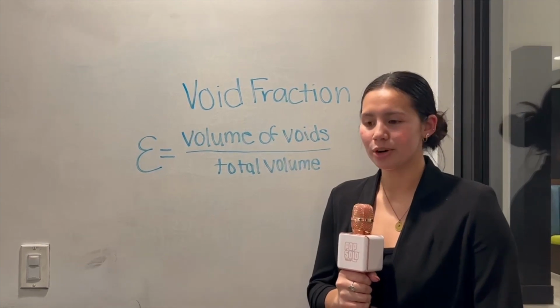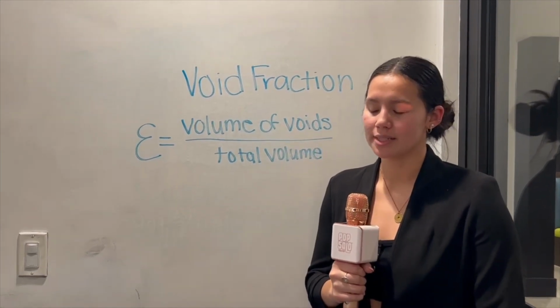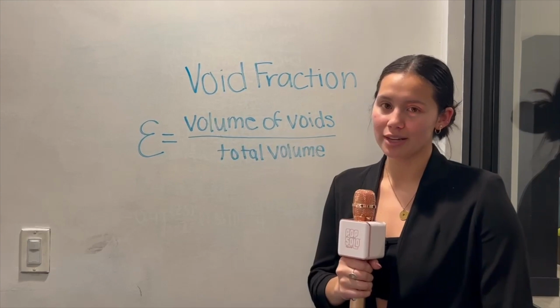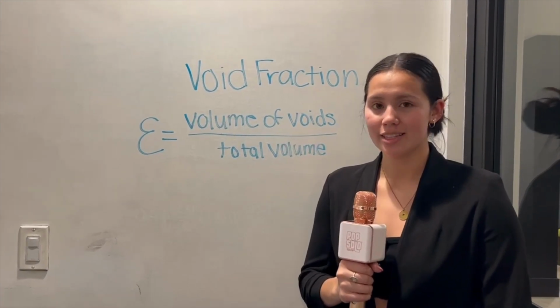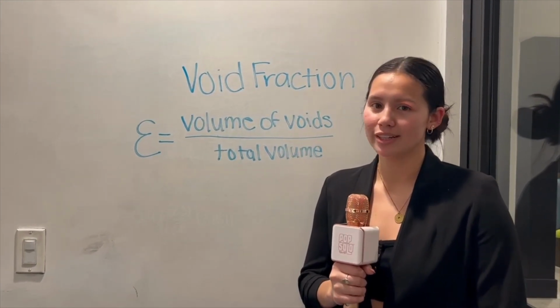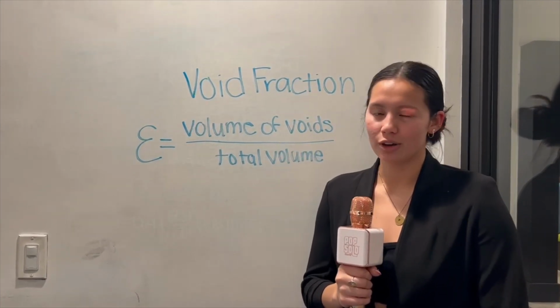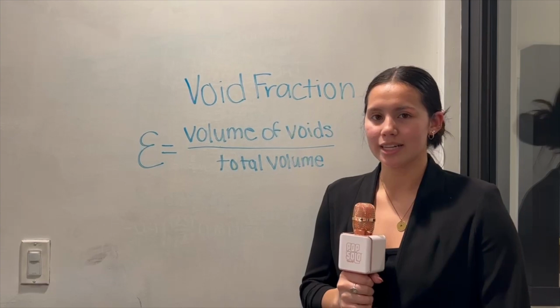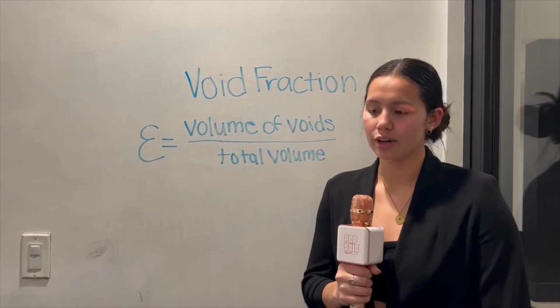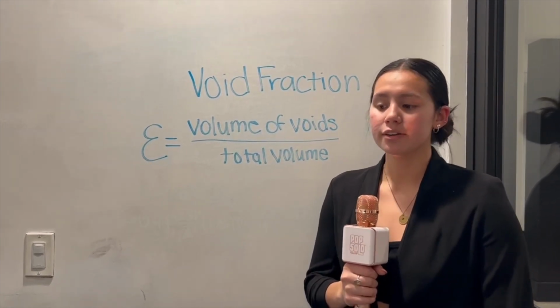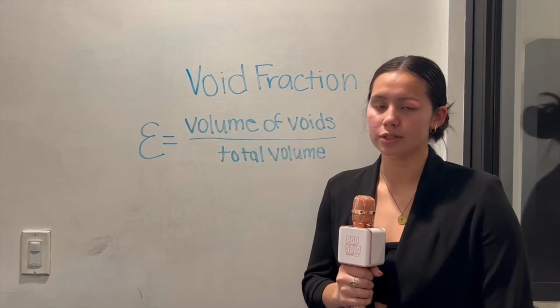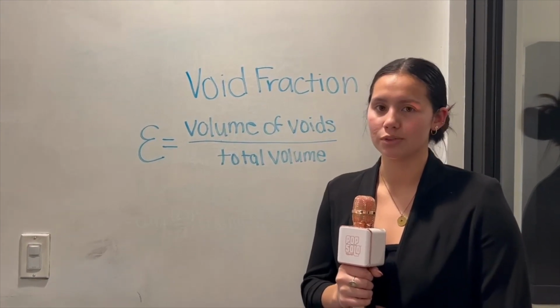This number is an important part of analyzing flow in packed beds. Packed beds are important in chemical processes for use in catalysis, adsorption, absorption, and so many more applications. The theoretical approach to solving relations for packed beds is regarding packed beds as a bundle of uniform tubes. Therefore, the void fraction comes into play when defining the fraction of void space where fluid can flow.